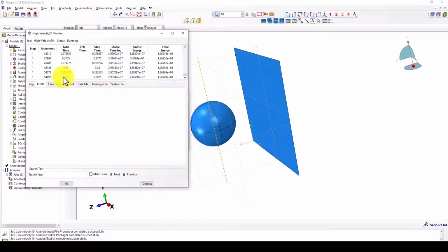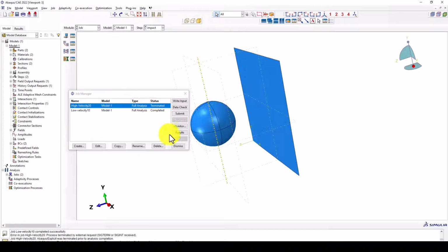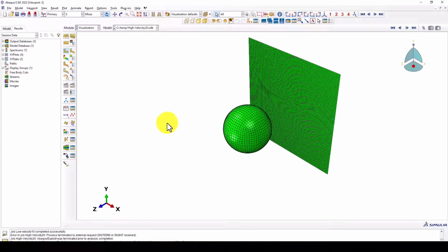So the main applications of stress transformation in simulation are understanding local stress on an inclined plane, finding principal stress in planes, finding maximum shear stress, which is equal to the radius of Mohr's circle, validation and verification, and design discussion, that is modifying material or geometry where stress concentration appears on the critical inclined plane or the critical planes.